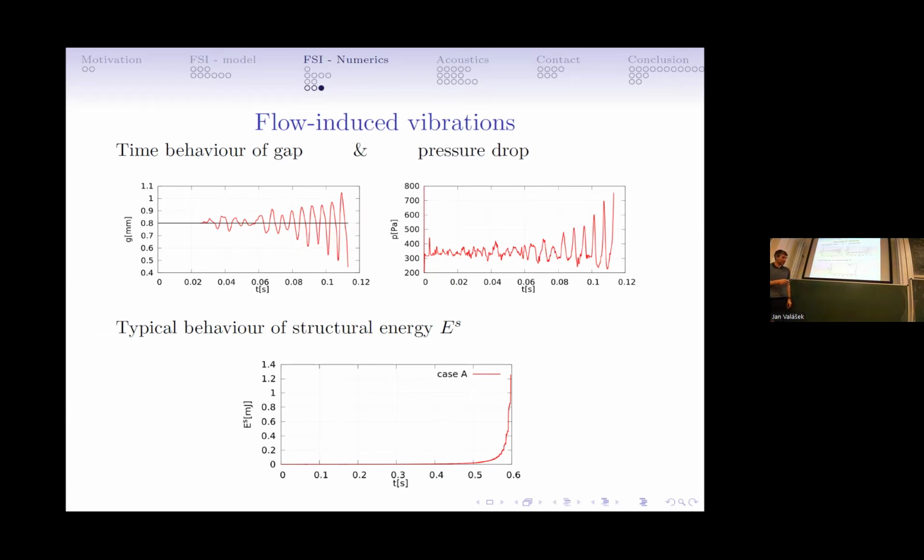And here, if we compute the structure velocity, the energy of the structure part, we also see an exponential increase in the structure energy. This is, as I mentioned, typical for these vocal folds, because this really happens in nature, and the fact that this is an instability doesn't represent a big issue, because at some point the exponentially increasing displacement is restricted by the mutual contact of these vocal folds.